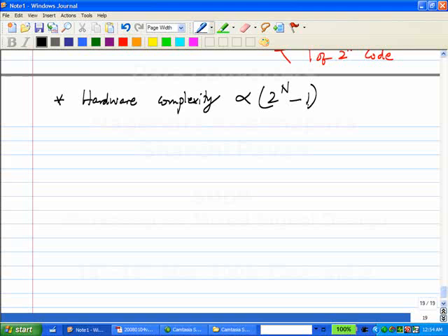So if you want to increase the resolution, right? If you want, for example, to reduce the step size by a factor of 2, how many extra comparators would you need? Reducing the step size by a factor of 2 means that I have twice the number of steps, which means that I need twice the amount of hardware, right? And twice the number of steps is equivalent to resolution wise how much? 1 bit at a time. Yes. Do others see this?